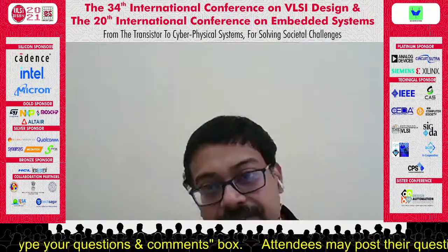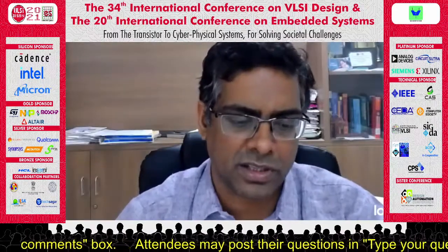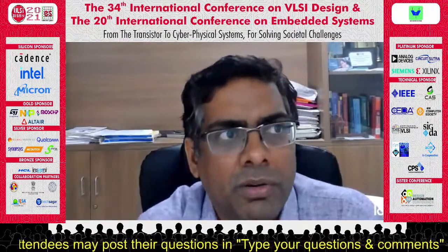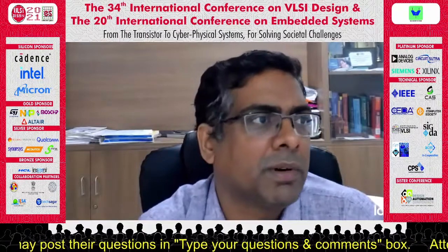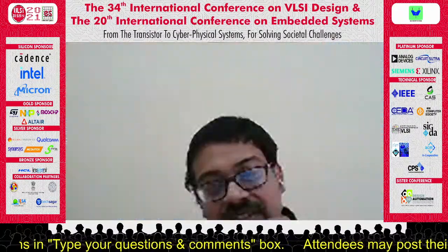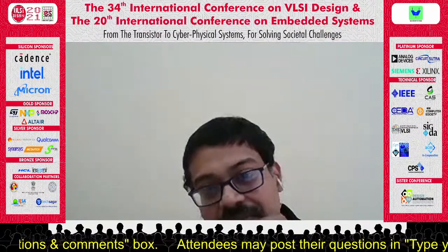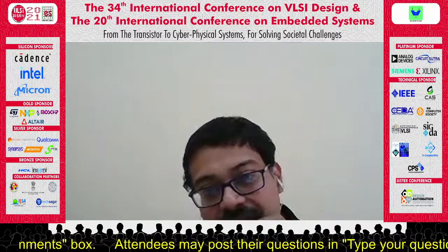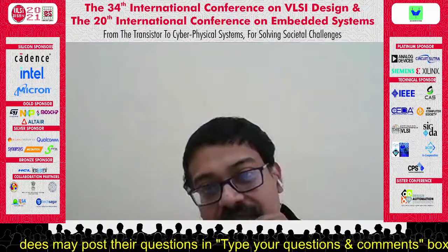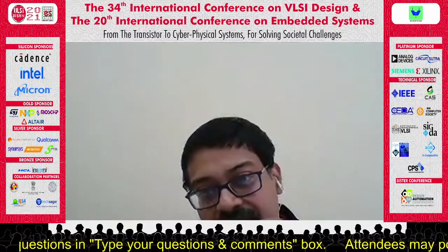Okay. And how do you calculate power? I understand that you have used gem5, but how do you calculate the power? The system has two parts, the memristor unit and the CPU. For the CPU, from gem5 we get the performance values, and we use those values in the McPAT model, which is based on CMOS technology.